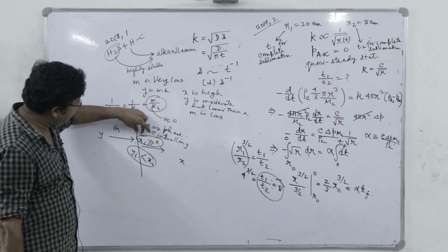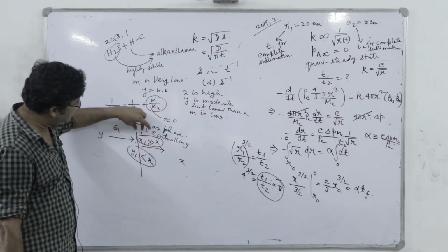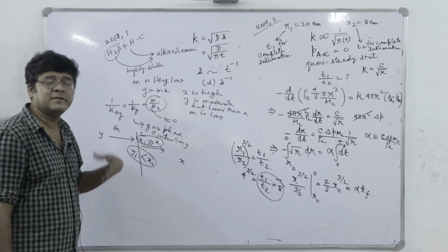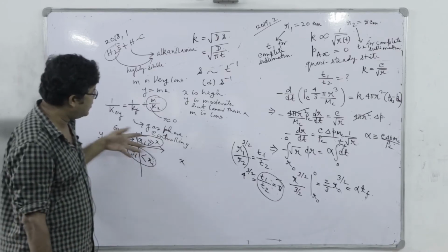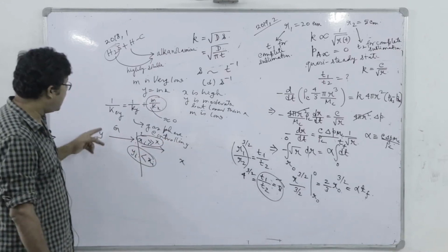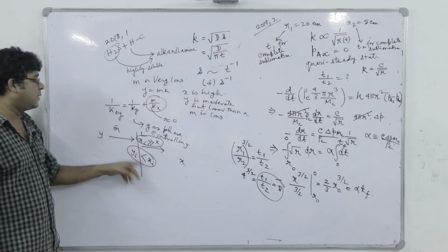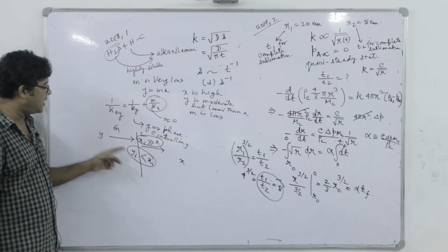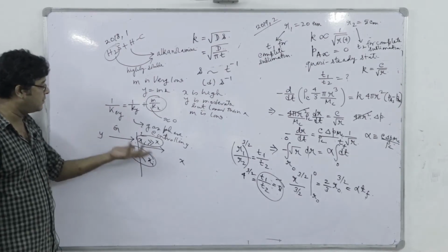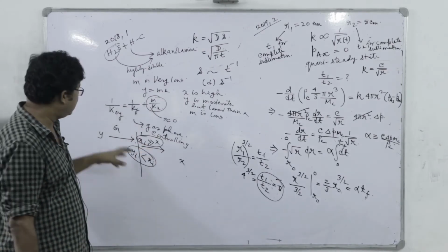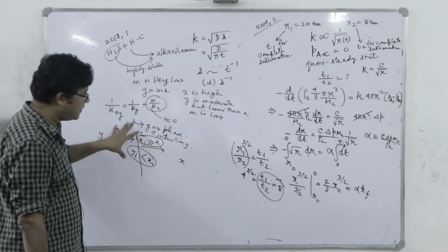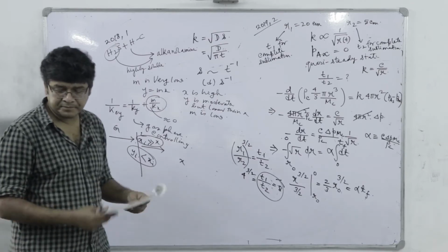If it is highly soluble, we will have high Xi. So as Xi increases, Xi minus X increases, so mass transfer is facilitated. However, Yi is much smaller than Xi, so Y minus Yi is not that much relative to Xi minus X, right. So accordingly, the gas phase resistance will dominate.